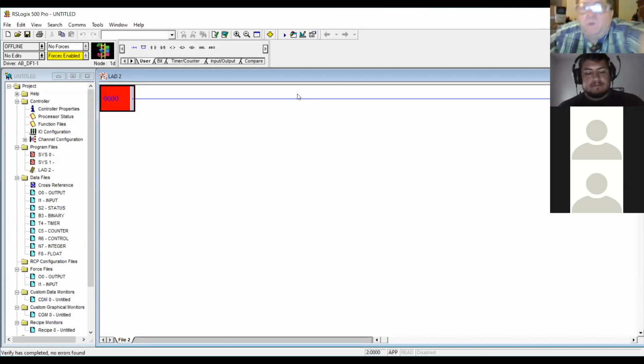Anyway, the stop button is wired into input 0. Now, one thing about the addresses here would be that when all of the inputs and outputs are built into the PLC, the inputs and outputs are considered to be in slot 0 when you're dealing with a MicroLogix, not slot 1 like on CompactLogix. On the CompactLogix that you've been writing logic for, the embedded I/O is in slot 1. In a MicroLogix, the embedded I/O built into the main unit of the PLC is called slot 0.